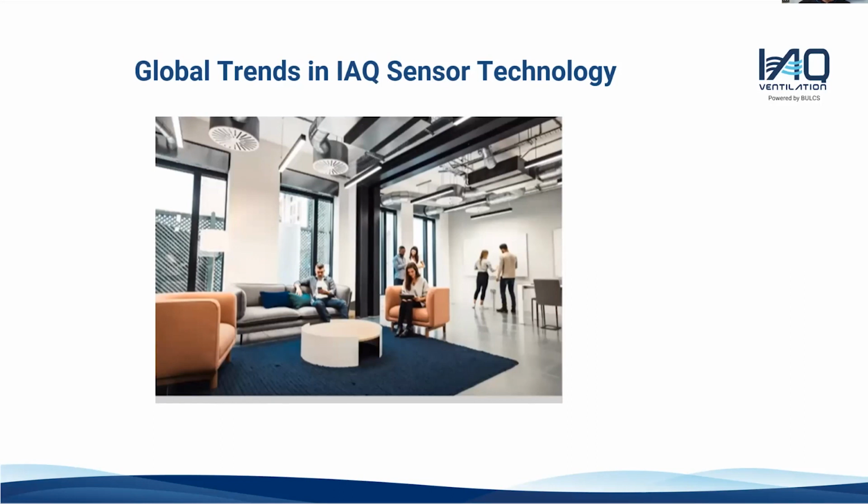In the past, sensors really just looked at temperature, humidity, and CO2. Now, with a lot of sustainability and wellness certifications coming in, we know there are more things we need to monitor. Sensors have expanded to look at VOC and particulates in different sizes.